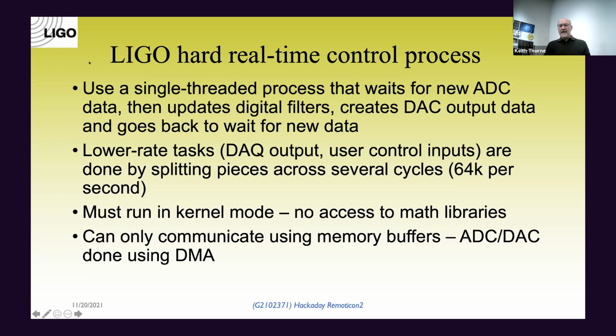And so you use DMA, direct memory access, a lot. So you just put it there and the D-to-A converters pull it out, or the ADCs put it there. That's how you talk to all the other processes you have that aren't real time, to talk to users and export data. So it worked.